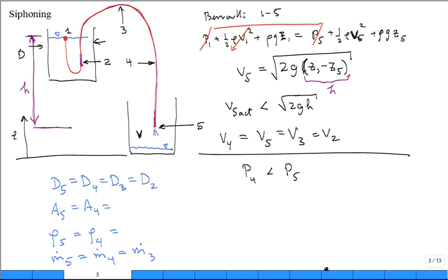All you need to do is step back and say, I used the principle of the fundamental theorem of calculus. Or I used L'Hopital's rule. We used the Bernoulli equation. That's music to my ears. You applied the Bernoulli equation between state 4 and state 5. The Bernoulli equation applies to any 2 points along the streamline. They don't have to be the endpoints. Often we put them at the endpoints, but they can be intermediate points as well, true?